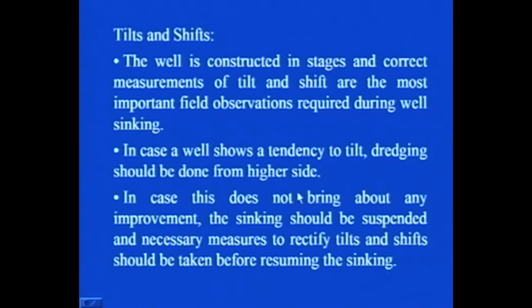So the side which moves more in the vertical direction is called the lower side, and the side which moves less is known as the higher side. In case dredging, more dredging towards the higher side, does not bring about any improvement, the sinking should be suspended and necessary measures to rectify tilts and shifts should be taken before resuming the sinking.